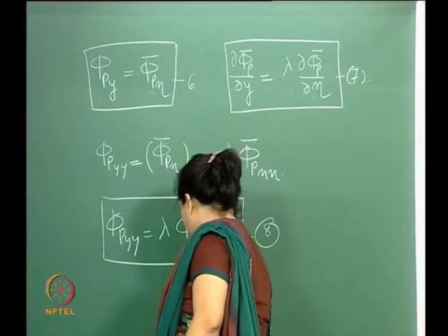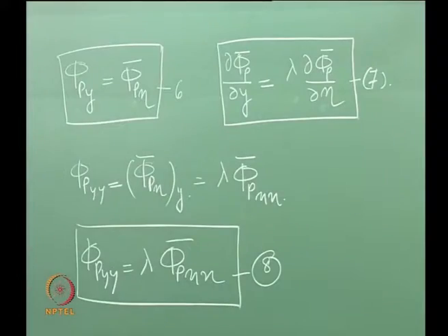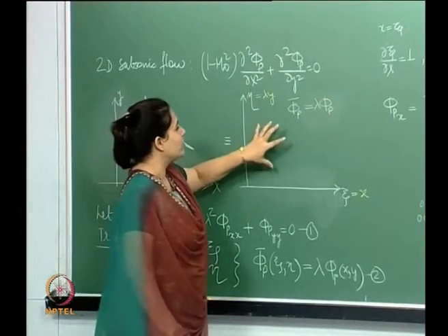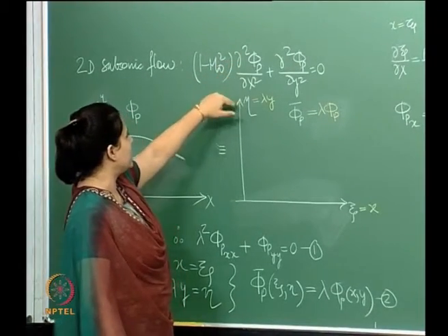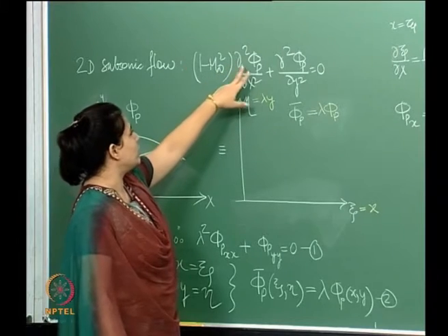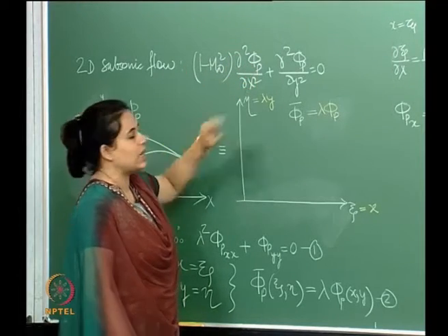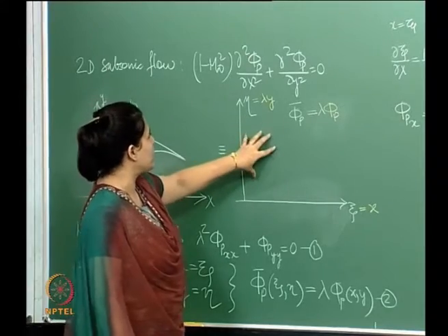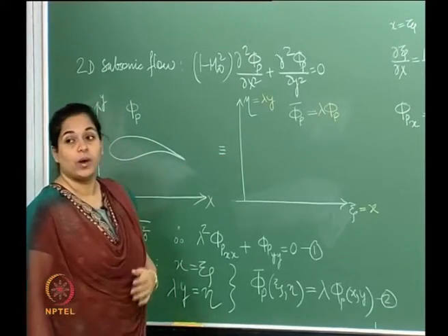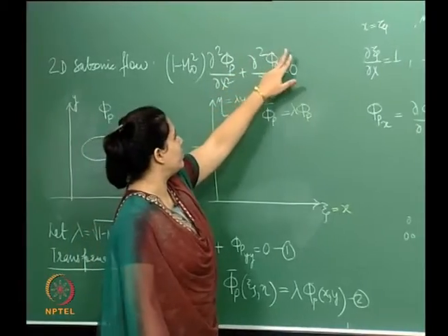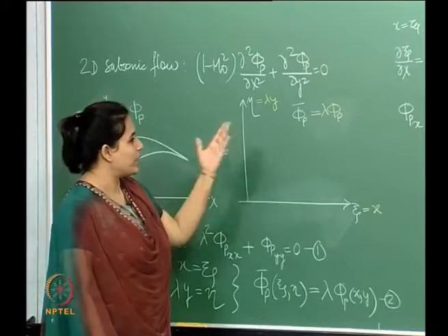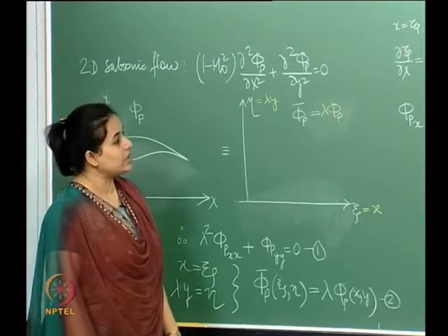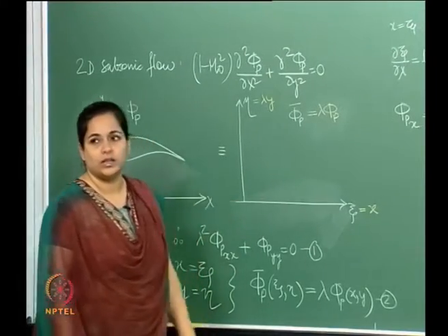The reason we are doing this, hopefully you can see, is that what we are looking to do here is see how this transforms into the transformed coordinates, our equation. So, we basically need to get a term equivalent to del 2 phi p del x 2. We need a term here which is del 2 phi p bar del z 2 and del 2 phi p bar del eta 2, right. That is why we went about doing all these things.